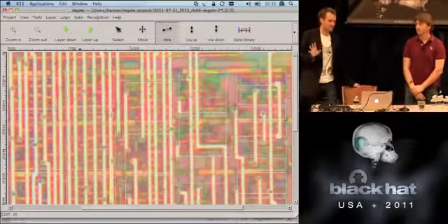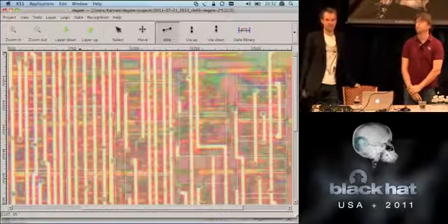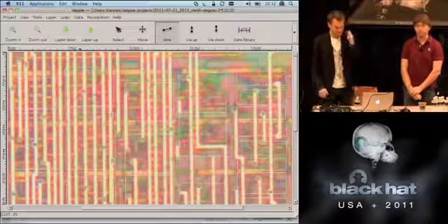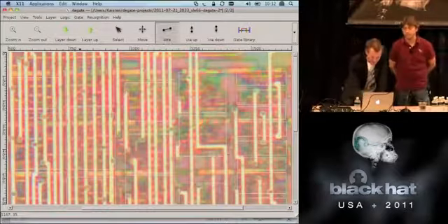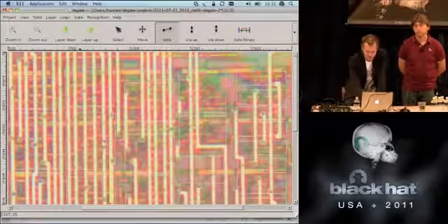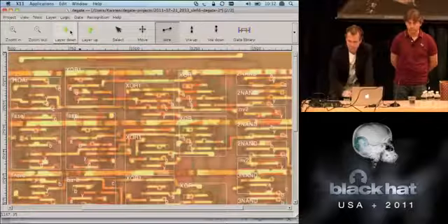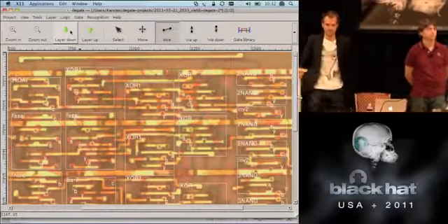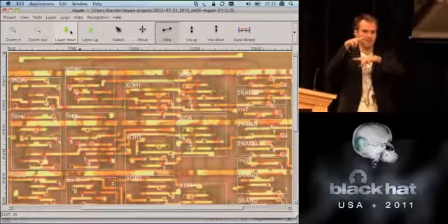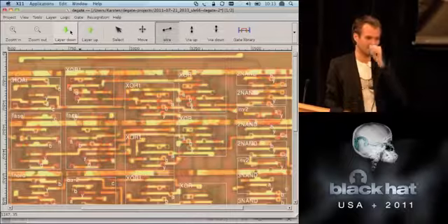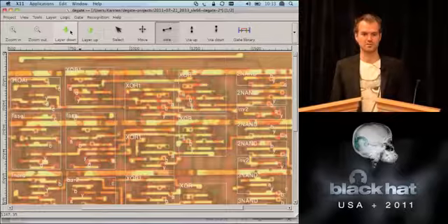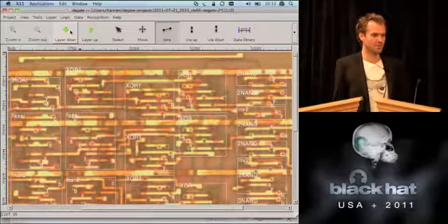There can be dead tracks, but everything still must be connected to something else. Right? So all that metal layer type obfuscation is of no relevance, really. So imagine somebody doing this for hours and hours, marking all these tracks on all the different layers. The tool then extracts the circuit diagram, right? It knows if there's a metal wire on top and there's a connection between two metal wires and there's a metal wire underneath, those are all connected to each other, right? So it then exports a very rudimentary Verilog representation of this chip, right?